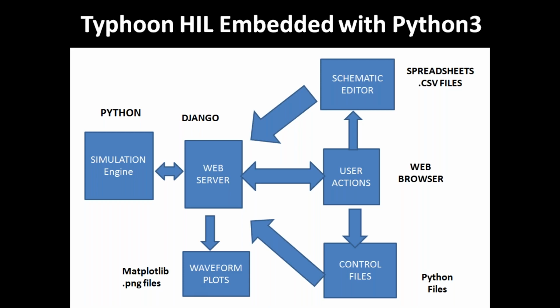If you want to have any result, like for the running waveform, if you want to save the data from a digital oscilloscope, then first you get the trace of that waveform, and a particular time you need to have. But with this you need not worry. You just go for it and save it in the .csv format. You will get the exact data along with the trace of the waveform.